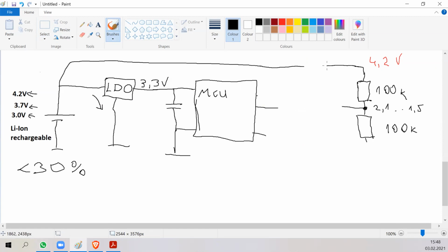And even old senior engineers sometimes make this mistake. I just recently had to correct one such mistake. So, P-channel MOSFET, P-channel and substrate, so the arrow is this. I'll also draw this internal built-in reverse diode, which is automatically inside all of the MOSFETs, so that you see that the current doesn't flow from the secondary side to the primary side.